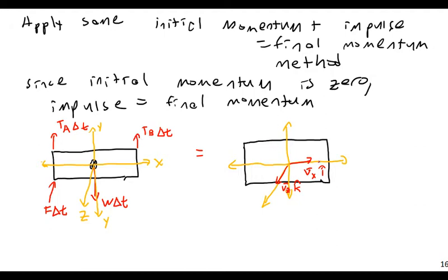Then, in terms of rotation, I will have something about the x-axis, which would be hx i. And then I wouldn't have any rotation about the z-axis because this is pointing in the same direction. I can't create rotation about the z-axis with a z-force, but I can definitely about the y. So we get hy j.